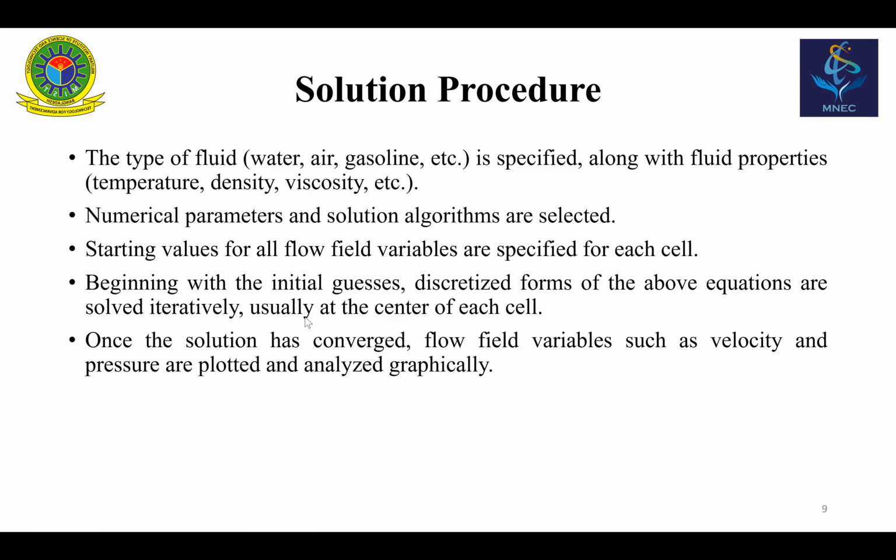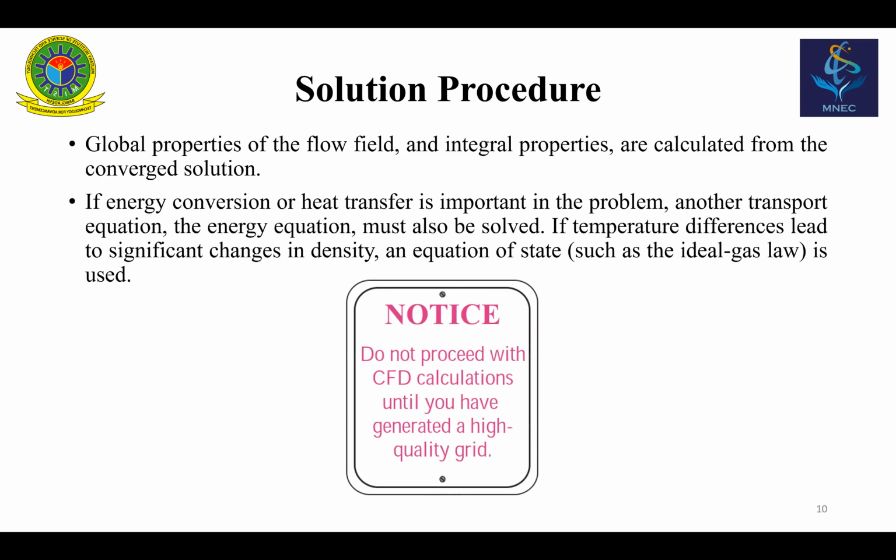If the solution doesn't converge, that means if the equations don't converge, then we have to think that we have made some mistake in the boundary condition, or we have to refine the mesh, or increase the number of meshes or grids within the system.